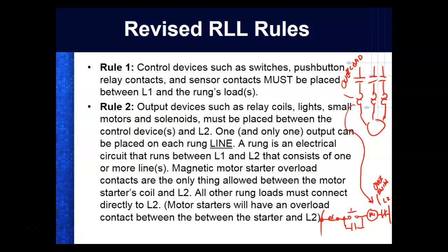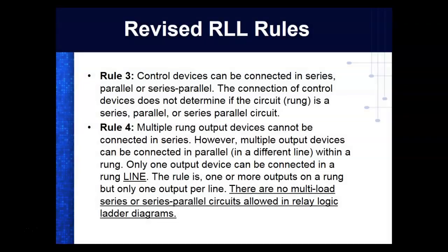The only thing that's allowed between the rung load and L2 is what we call a magnetic motor starter. Rule 3, control devices can be connected in series, parallel, or series parallel. The connection of control devices does not determine if the circuit is series, parallel, or series parallel. What determines that is the way we connect our loads.